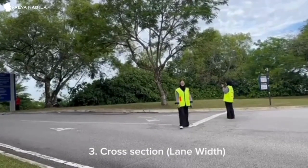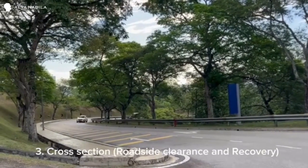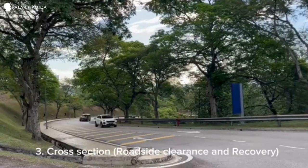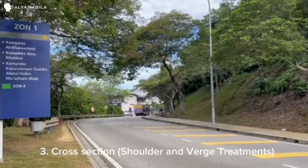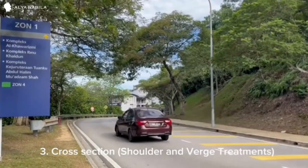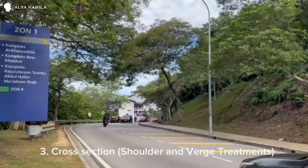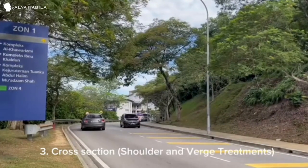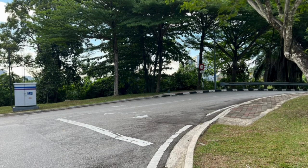A cross-section includes everything you see if the road is cut sideways, like lanes, shoulders, and the road sides. The lane width was just enough for safe vehicle movement, but not too wide, to avoid encouraging speeding. While for the roadside clearance and recovery, it can be seen that there is no safe clearance between the edge and the roadside of the road, where big trees are all along the roadside. Lastly, the shoulders and the verges do not have adequate shoulder width to help alert the drivers who drift off the lane.